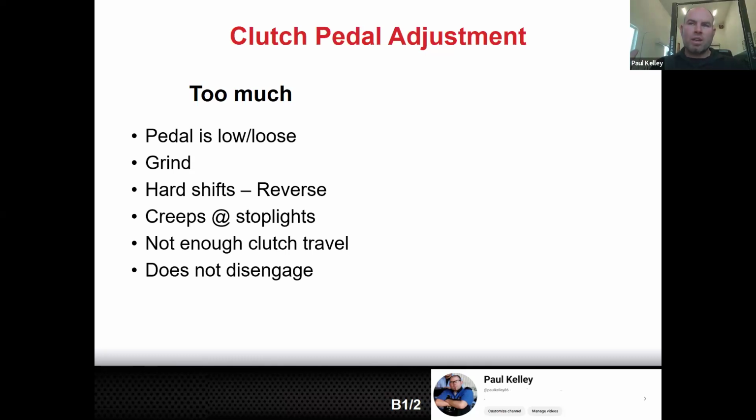And then at that point, you could feel it in the pedal. You'd go to throw the pedal all the way, and the pedal would stop like an inch off the ground because it was bottoming out the clutch. He spent like a couple days on it. And then the kid came back to me like, hey, can you have your buddy at Automatics fix this? And I was sort of like, well, didn't he tell you need to get an OEM clutch and not the purple clutch? And he's like, yeah, and I'm ready because I've already bought a master cylinder and a slave cylinder and all this stuff.